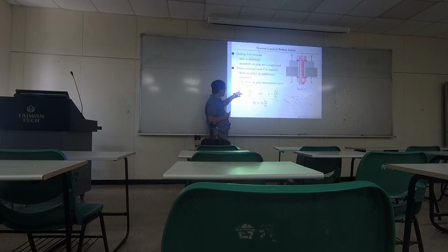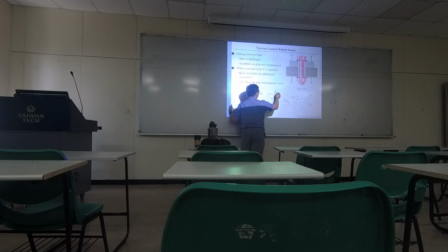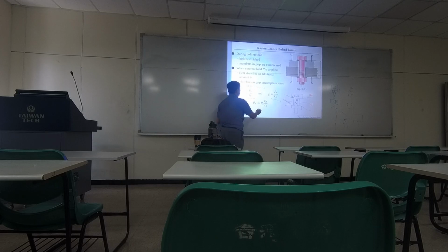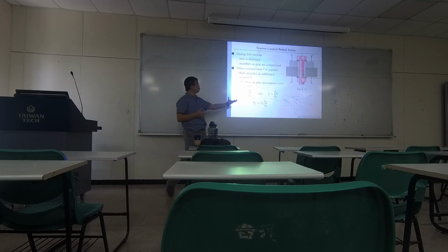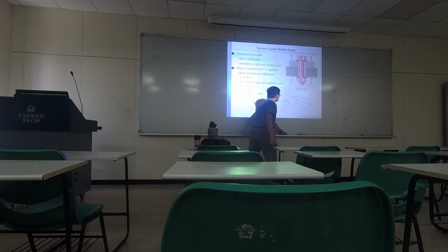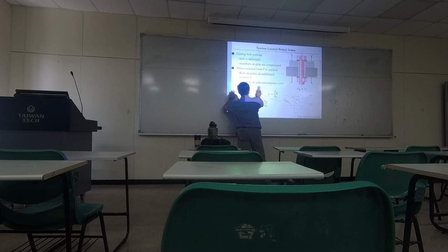Then you can figure out there are some forces inside, and you can use them to compute the relationship between the force inside the bolt and the force inside the member. And since it's the same amount of deflection, these two equations can be combined together. Okay, so what's next?